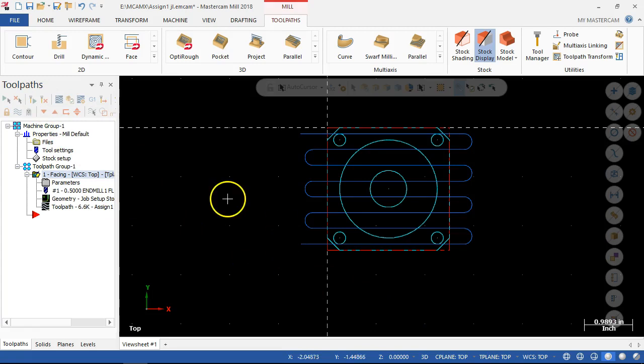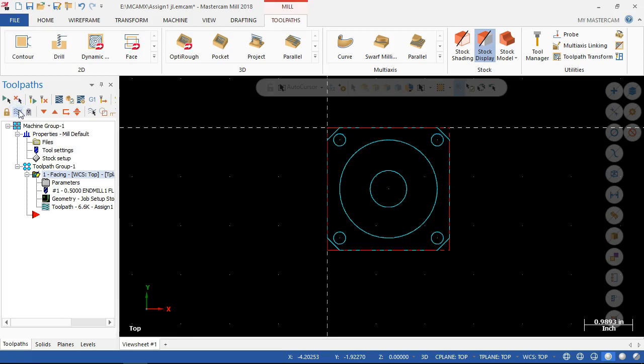So let's go into the operations. We want to hide show. So continuing on, these are going to be the simulation, the post. Toggle the locking on selected operations, so you don't want them to be adjusted without unlocking. My screen is going to get kind of cluttered, so toggle the display. That turns the toolpath on. It does not delete it. It does not lose it. And then if we ghost it, the little ghost icon there, it's going to say don't post that operation.